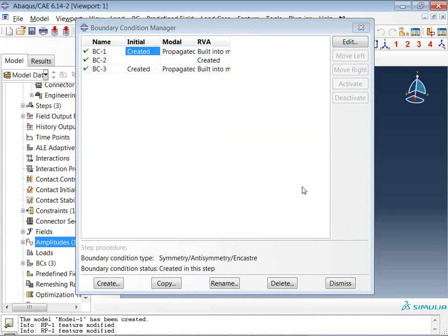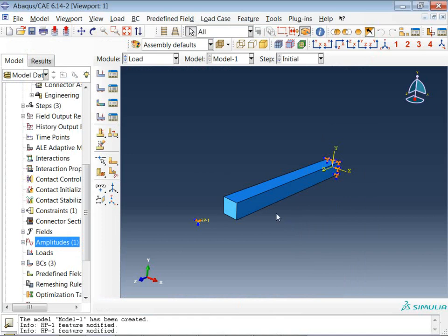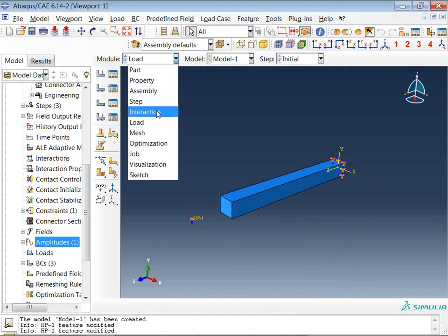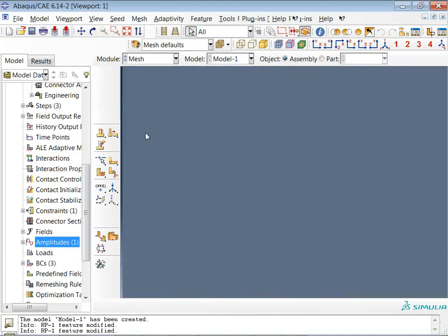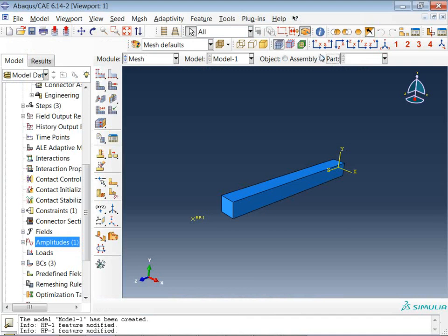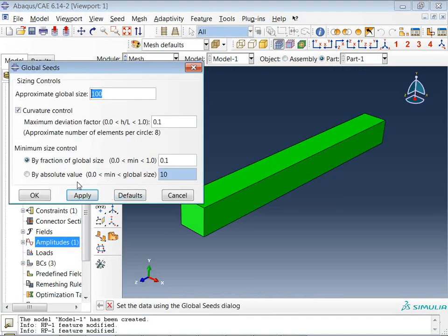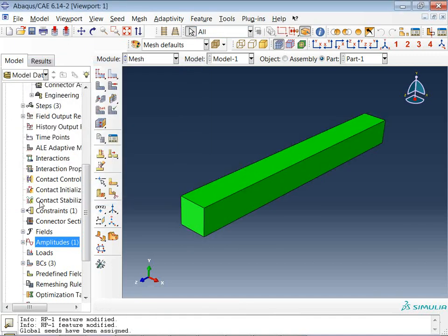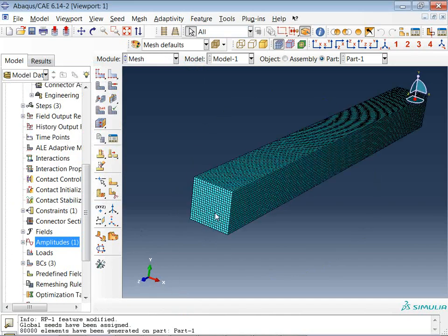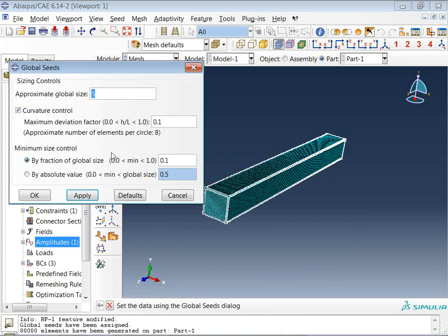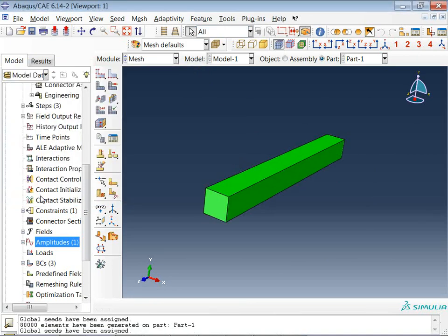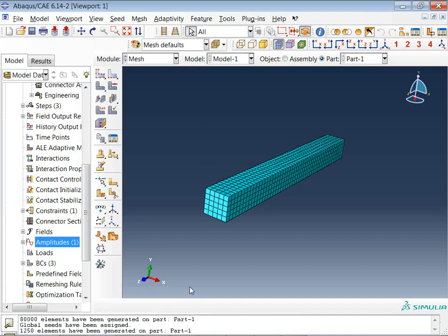The same thing for your frequency response, the default outputs are there: A, L, U, S. For that particular one, we can also take the root mean square, and for the stress, von Mises is sufficient. Okay, so this is the required output we are requesting for our particular solution.